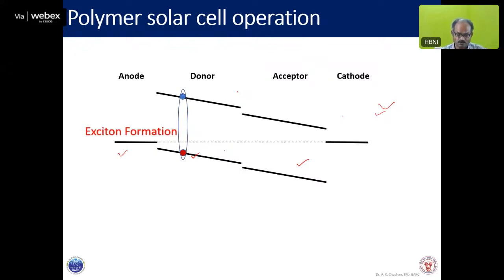These are not a free electron hole pair. Actually, it is an exciton. Consider them together, though the energy is higher. Now this is electrically neutral. So even if you can see a gradient of potential, we consider the built-in potential due to the difference of work function of this and this material.